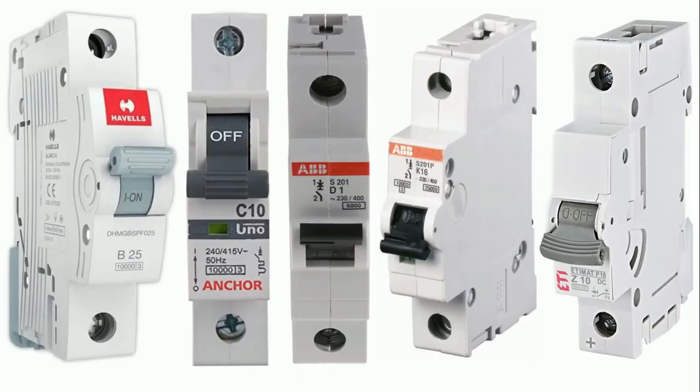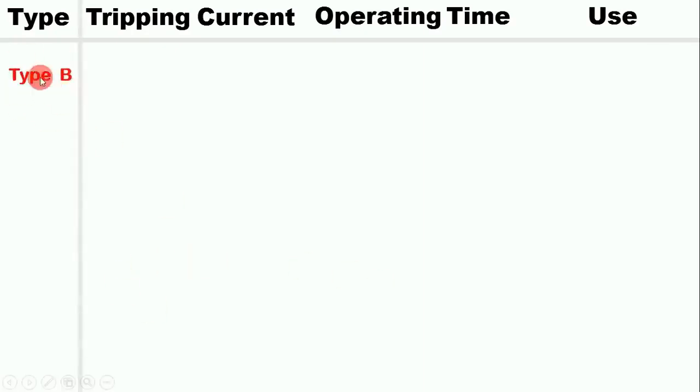Okay then, now I will tell you about 4 things. First is type, second tripping current, third operating time, and after that we will see about uses also. So friends, first I am discussing the B type MCB. Friends, the B type MCB you use, the tripping current of this is 3 to 5 times.